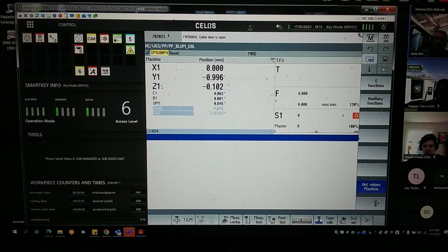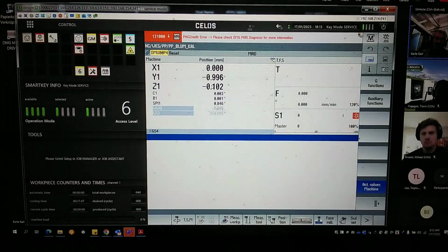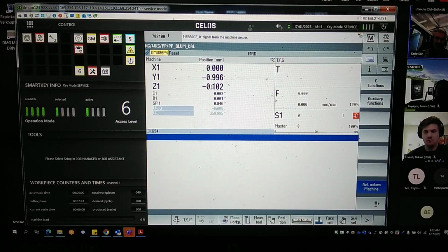That means the axis designation letter is indicated with the extended value 1, and that means the right coordinate system is active: machine coordinates. Machine coordinates show you the position independent of the used 0-point offset, directly in relation to the reference point, the axis 0 position, the absolute 0 position, okay?